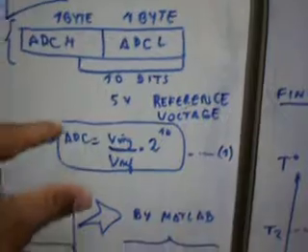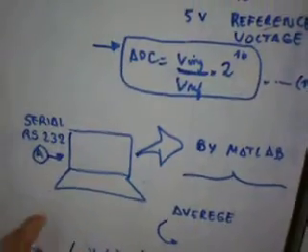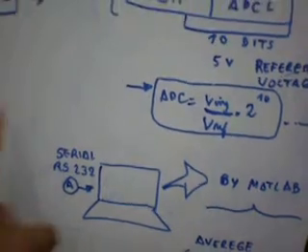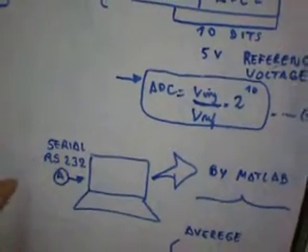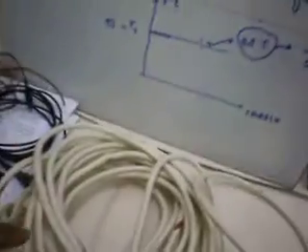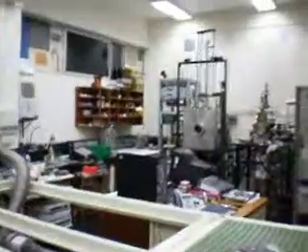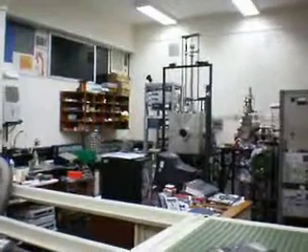Okay, and this signal is going to travel to the personal computer, specifically by the communication, I decided on serial RS232, by this cable, just around 2 meters, because the chamber is far from here, at a distance of 10 or 12 meters.